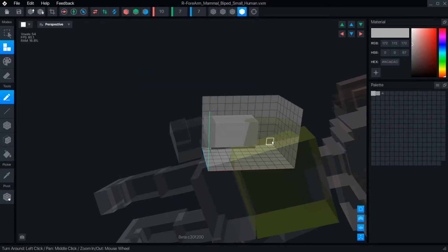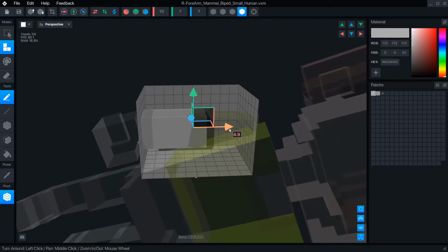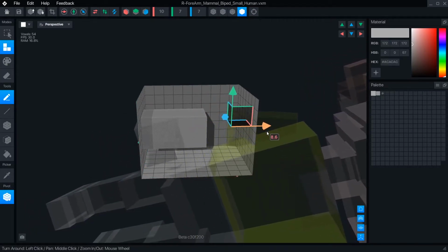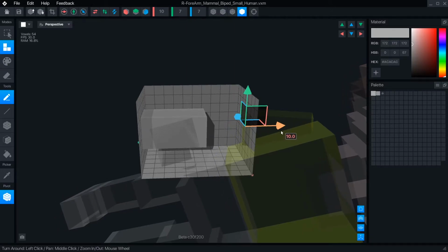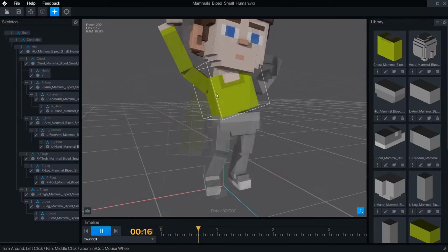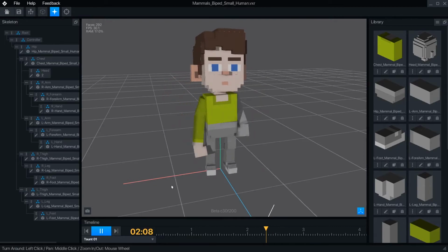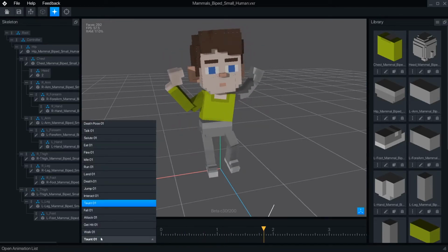If significant changes are made to the model geometry, you might need to adjust the pivot point. This is most helpful when you can see the rest of the rig's ghost, so you can line up the joint correctly. Small adjustments to the template pivots often work fine, but making changes that are too big can easily break the animations, with joints separating in terrifying ways.